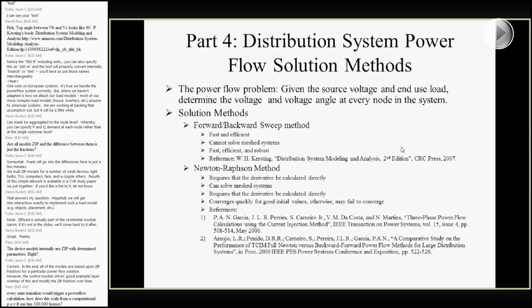Some of the other studies, for example, if you want to start looking at solar transients, when you want to look at cloud passage over a solar panel and you want to focus down on a really tight 45-second window, then that's when we'll make our minimum time step something like a second, and we'll make sure that all these devices are actually sharing their information at 1 second intervals rather than 1 minute intervals. So that's one way that we've gotten around it.